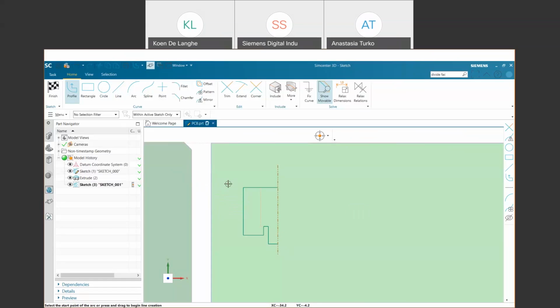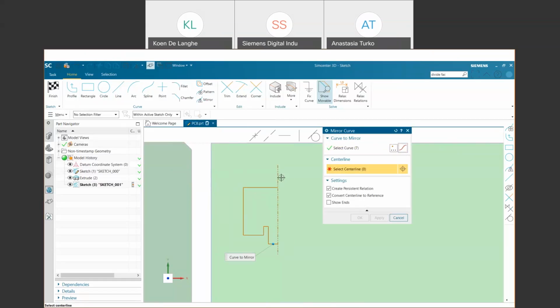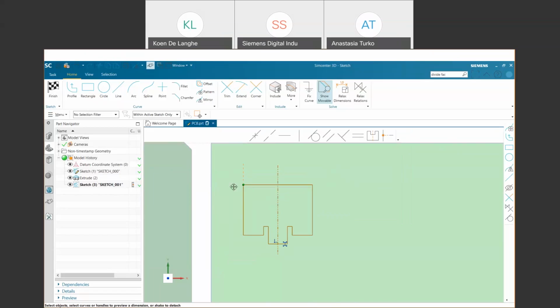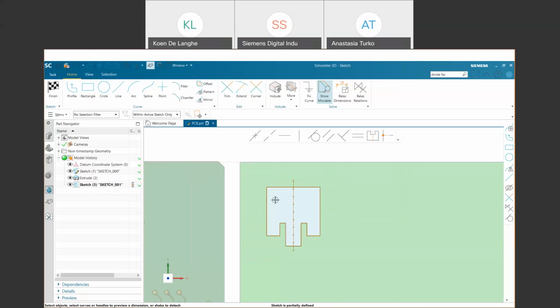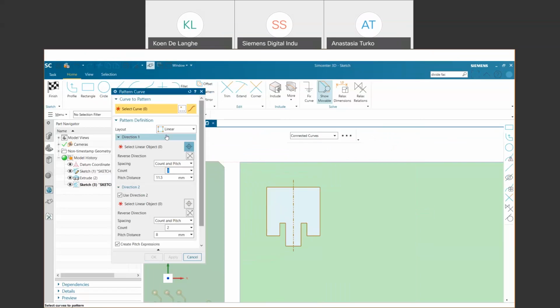So here, it's a very easy way. You draw your antenna. You can basically now mirror that shape here. So you select, just a moment, you select the shape. You mirror that. Okay. So here we have a very simple first patch that is completely parametric. So it's very easy to make and to really put parameters on the different geometric properties. This is just one patch. If you want to pattern the patch into, for example, multi-patch or for MIMO purposes, you can select that.